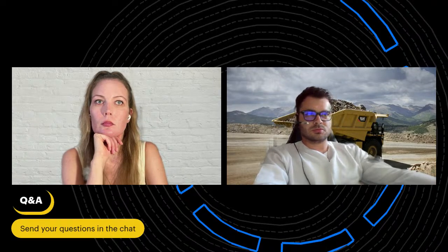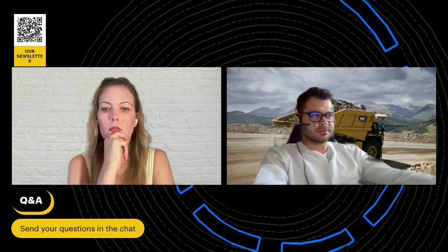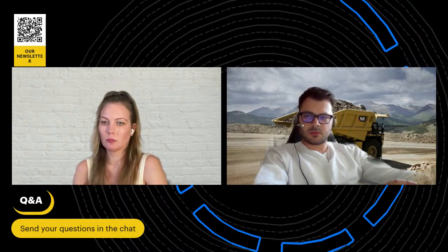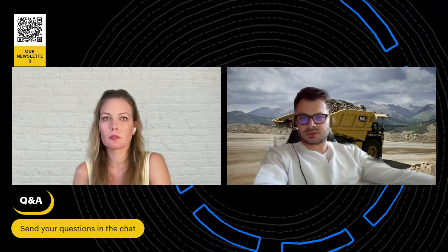You should also avoid the horizontal intersections that we tried to prove to you during today's stream. Then it should be a straight slope during the haul road. And what is the most important, I think, for a mining engineer during construction of the road is that the engineer should clearly see different mining phases. I mean, different pushbacks. Different pushbacks should be connected together with these roads. There shouldn't be any gaps because in this case, the mining will just stop.